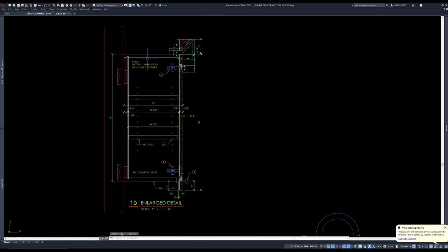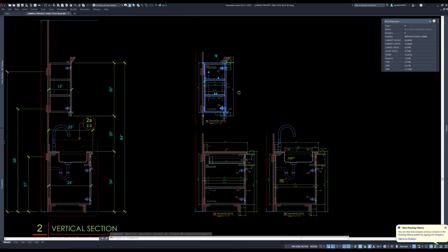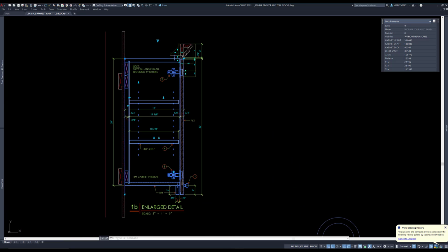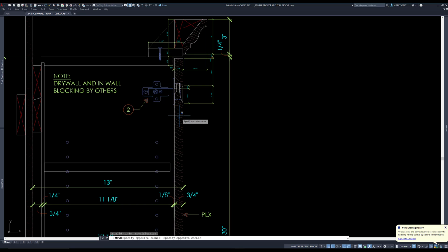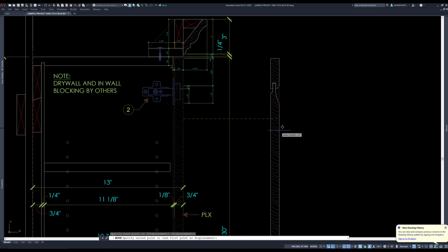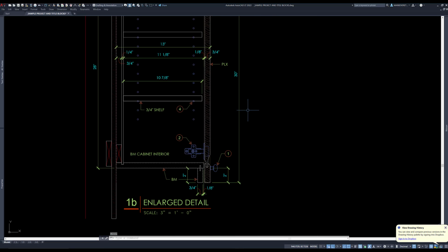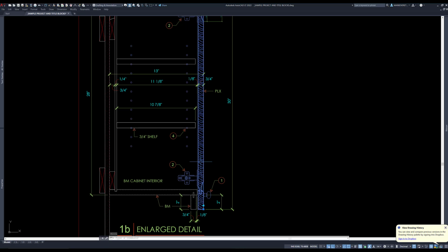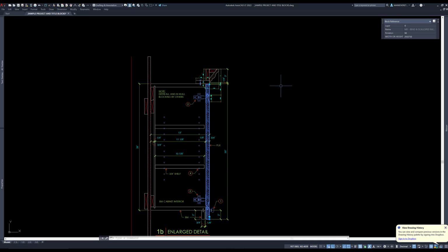I took basically the cabinet section that was here in the previous demonstration, the sample drawing, and I've just basically renamed it. And then if I move this panel here off to the side, let's say 6 inches with my ortho, you can see that there's a line there. It's kind of my guide, but it's on the depth point layer, so it does not print out. It just allows me to have a nice guide so I can stretch this raised panel block to accommodate that, but everything else about the block is the same as before.